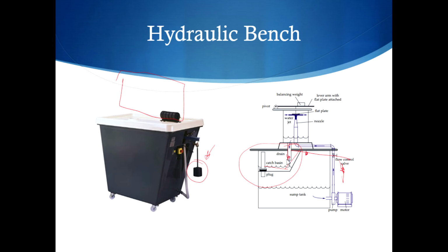When the water reaches a certain weight, we have a plug in here, and the tank and the plug will open. For example, we have a weight of 12 kilograms. When the tank reaches 12 kilograms, the plug will open and the water will start draining. That is when we have to stop our watch, because when the plug opens it means that it reached the weight, and then we can calculate a flow rate.